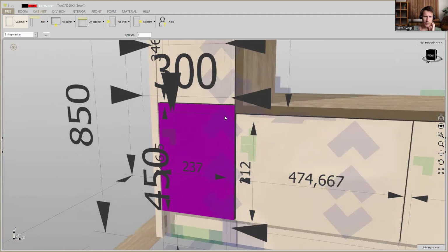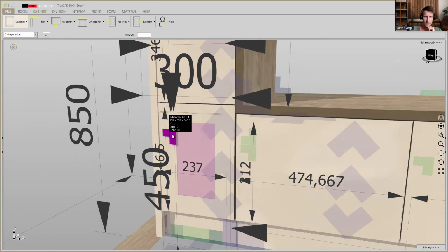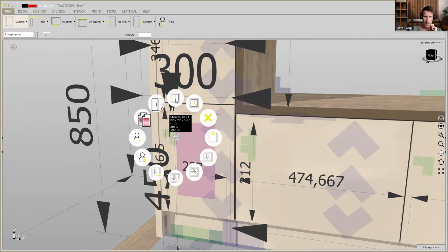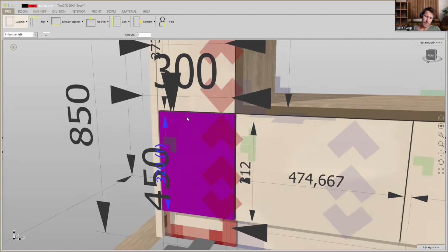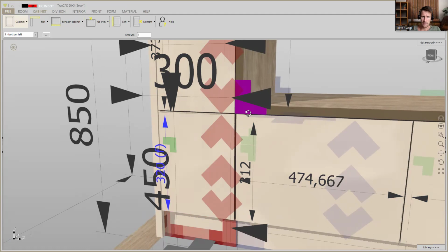So we are going here on a smart click for this bottom left area, click on it, go on height, and here you see the current height is 346.5. We say equals 346.5 minus 26.5, and it's calculating to 320 millimeter, like you see here, blue. And the F means it's now fixed.